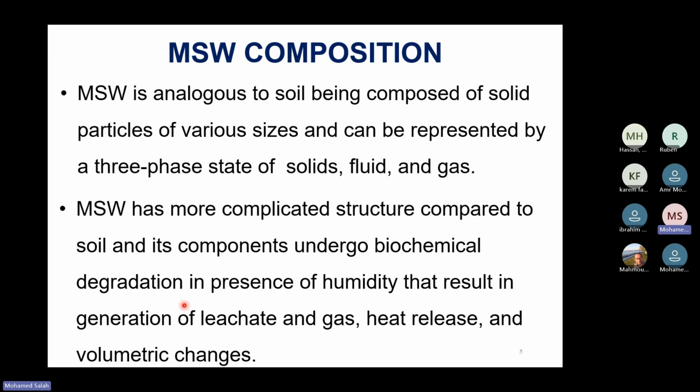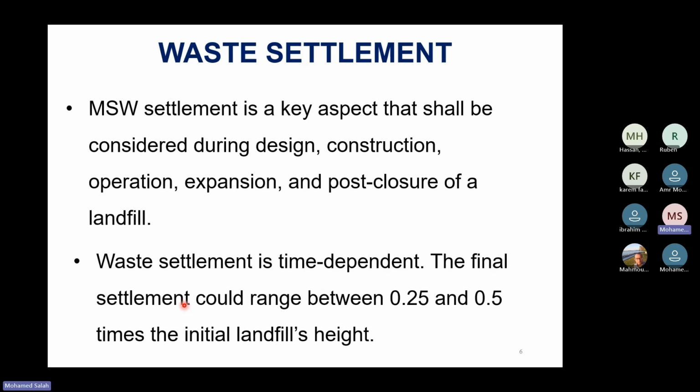This results in the generation of leachate and gas, heat release, and volumetric changes. Therefore, the settlement of waste is considered a key aspect that should be taken into account during the design, construction, operation, expansion, and post-closure of a landfill.